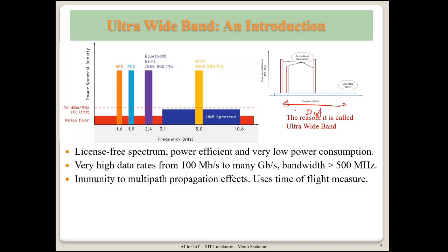Okay, if you know the transmission rate in meters per second, and suppose at the receiver you know the transmitter is expected to send a pulse at this time, and the receiver receives it at T2. Suppose the receiver is aware of that information, then based on the time delay in receiving the pulse, it will be able to guess how far it is from the transmitter.